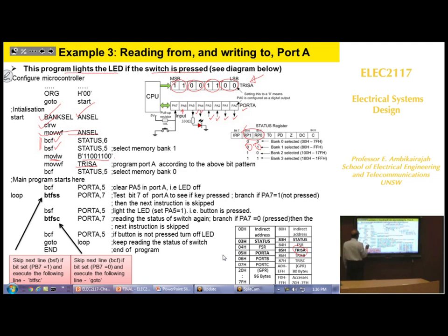Done? Now we are going to go to port A access. You can say BANKSEL PORTA, or go back and change this value to 0. That's what I've done. I set the bank to 0, then my port is ready.